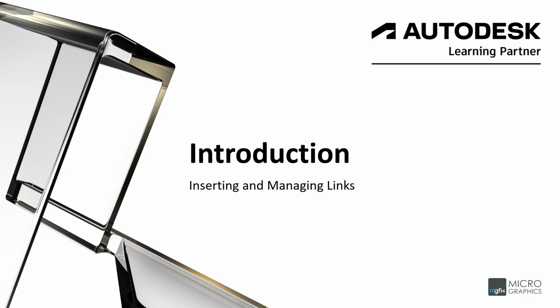Okay, so as an introduction and overview, I'll show you how to link both CAD drawings and Revit models into your project, and then we'll explore how to manage those links using tools like reload, reload from, show the link in the model, unload and remove functionalities. Revit links are an essential part of collaboration. They help us keep our projects light, coordinated with consultants, and make updates quickly.